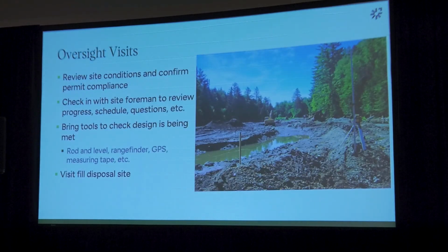So along with that communication, when we're on site, we're looking at what's going on, what phase they're in, talking with the site foreman about anything that's come up while we weren't there, talking through the next steps, where they're going to move to next. Are they going to be moving the water to a different channel so that we can make a good plan for that? And making sure we have the tools in place to be able to check slopes and things. It works really well to do those checks with the contractor, but if you get to the site and they're not there, it's good to make sure you're prepared. And really checking where the fill goes, because as has been covered, it's important where it's going to.